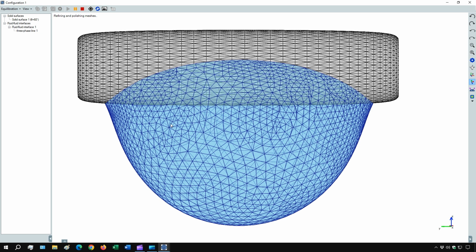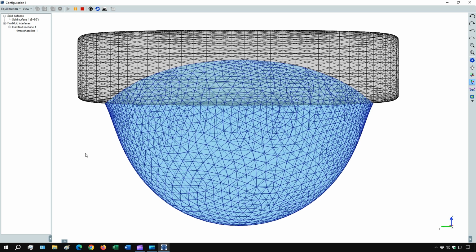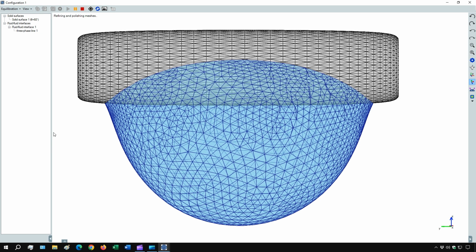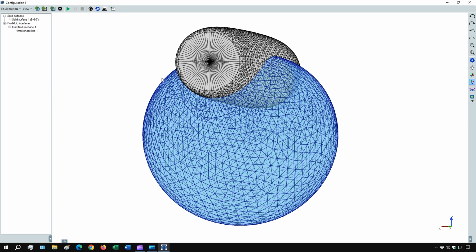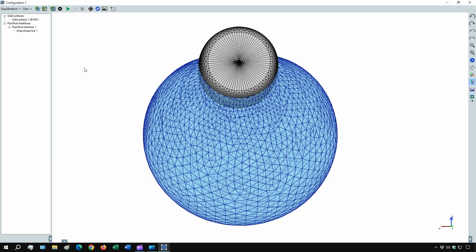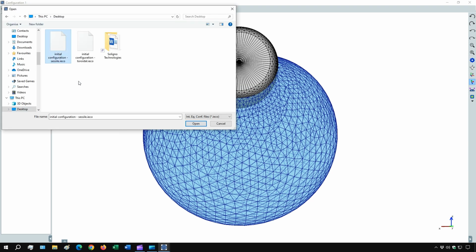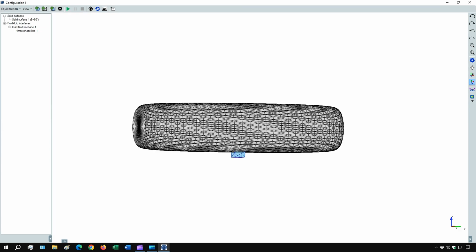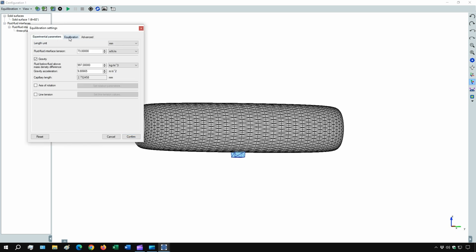And so we have obtained the droplet's equilibrium shape with a more refined mesh. Now I want to see if the sessile droplet topology is stable, also for the contact angle that before gave us a stable toroidal droplet. So, I reloaded the initial configuration with the fluid interface mesh having a sessile droplet topology.